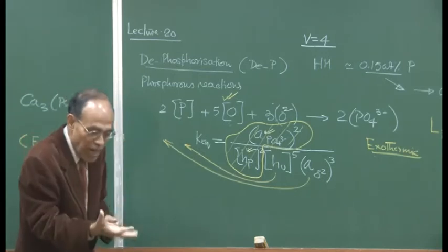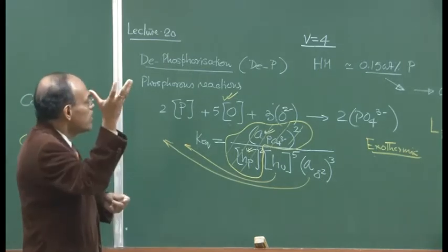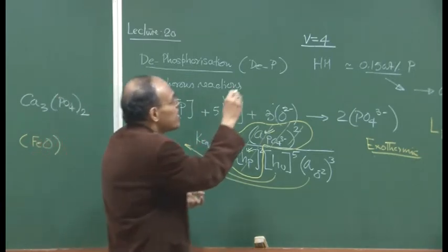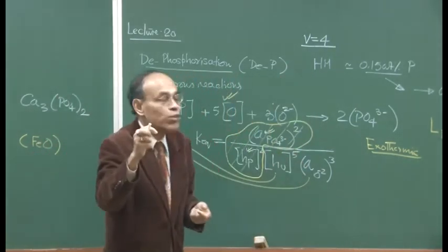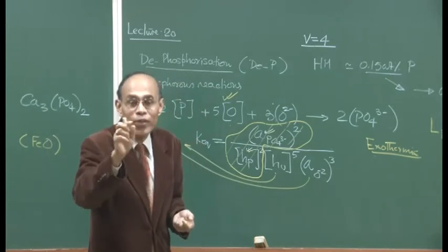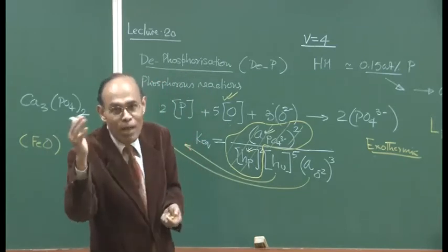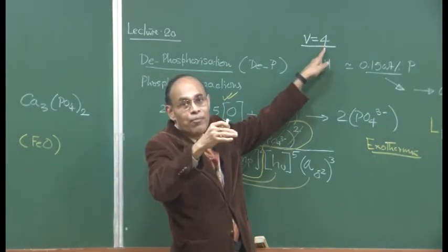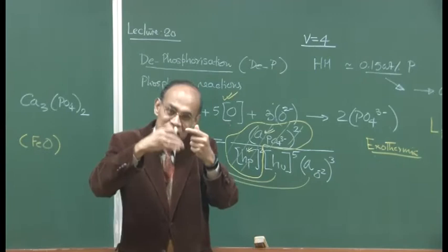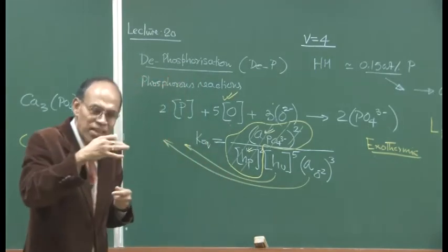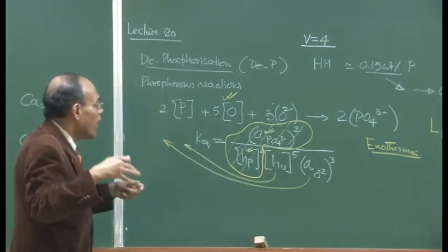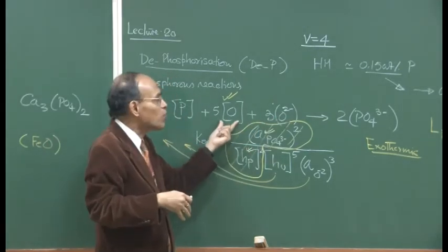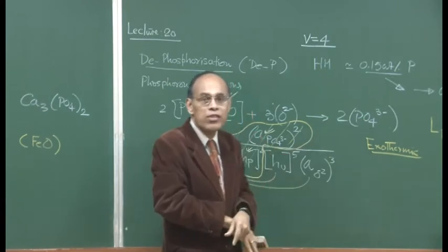Of course, you have large scale silicon oxidation, you have large scale heat generation, as a result of which the lime starts to dissolve, and because the basicity develops, the first slag to form will still be FeO-SiO2, and then progressively lime will dissolve, lime will replace FeO. So to get to this particular value of 4, it will take some time. So during the period I am talking about, the basicity is developing, the temperature is not too high, and the slag is not too basic.